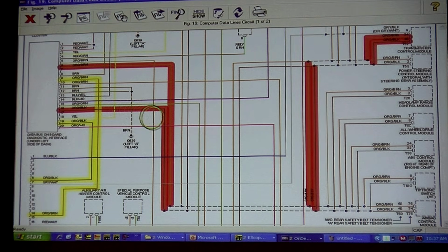Here, I come up and we come out of my bridge and we come over and we're hardwired and we start splitting it. Do you see all these splits and do you see how that goes to the tranny? Okay, now I know how I'm wired. At least I have an idea. And I know I'm not directly on the bus, right? I'm going to show you these, but I did not come out of this into pin junctions where I'm directly on the bus. I went to some kind of an interface. And those interfaces are always going to change the way that we communicate on the bus.